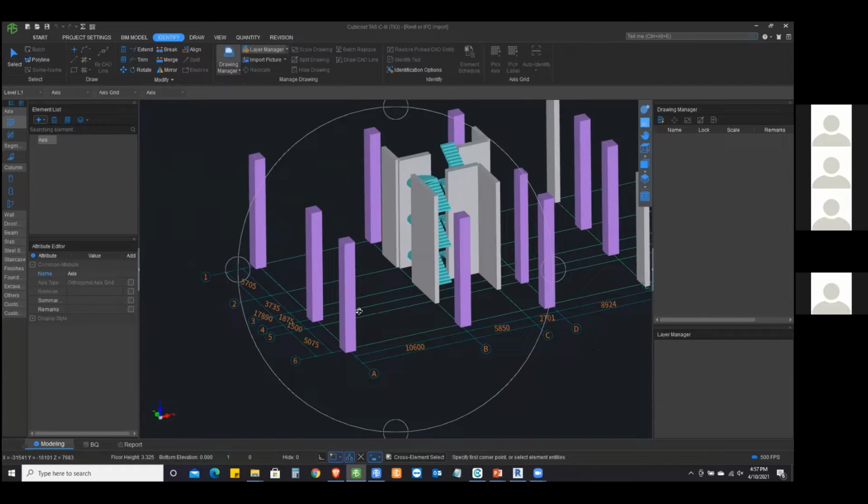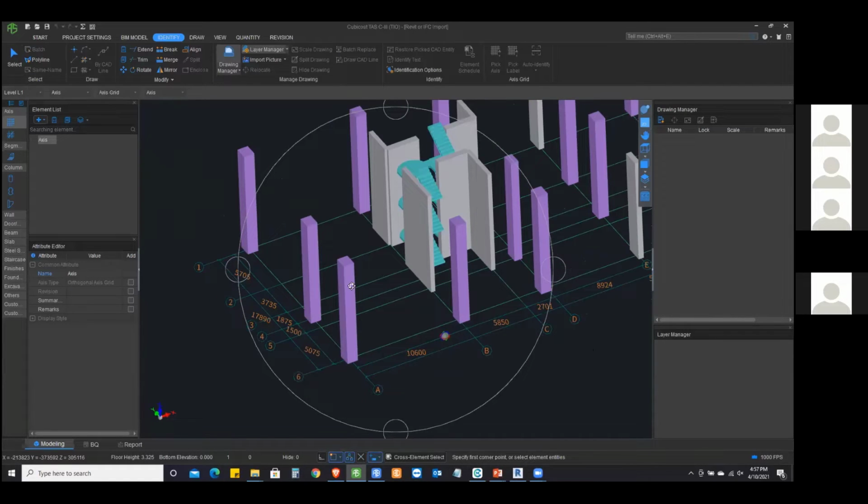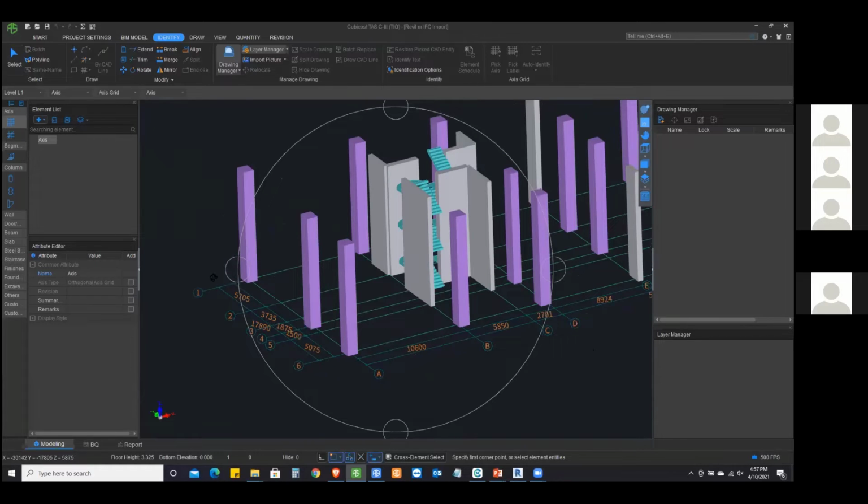If you follow the guideline, you have to cut it off at that location, instead of providing that inside of your Revit properties. You provide that information where it should be for a particular column. That should not go all the way to the top. You have to separate it in order to get separate quantities. So that's a condition there.